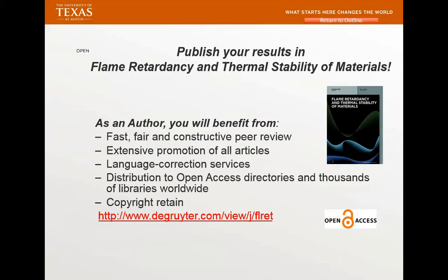They are my partner. I also have PBI, they are my partner. So I will get the material, and we basically will do the experiment. And instead of using a small amount of nylon, we're able to use 20% flame retardant nylon. We were able to extrude the fiber and actually put it in the fabric. I think we actually published that.